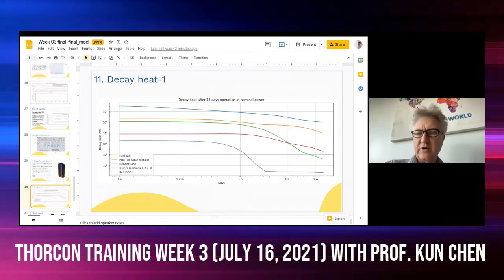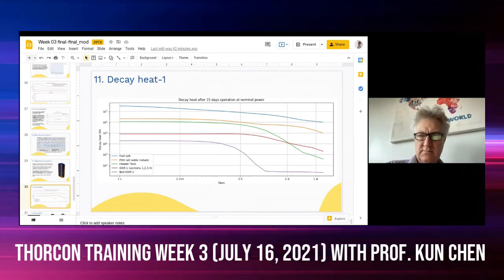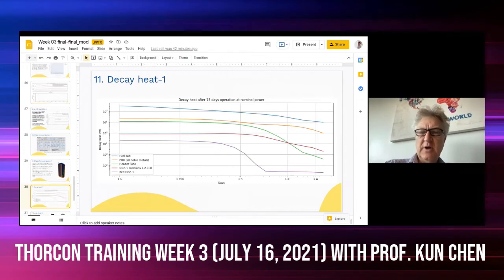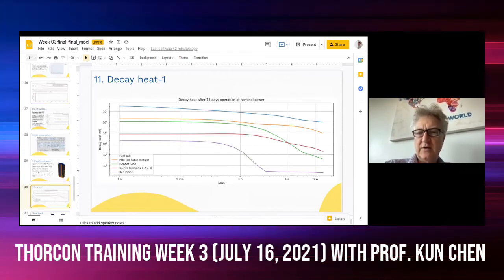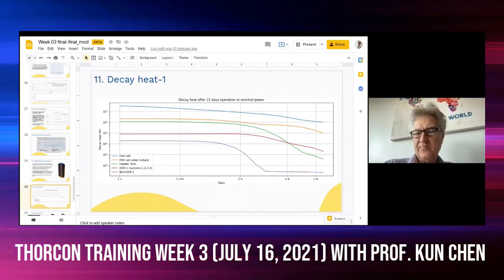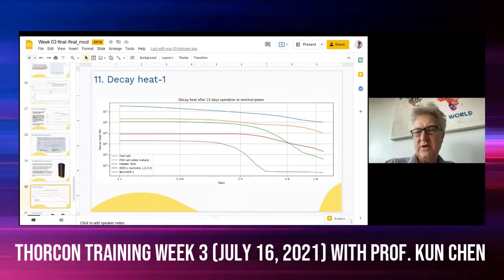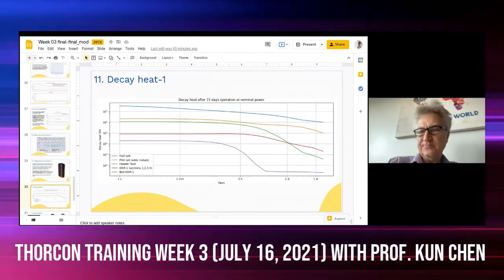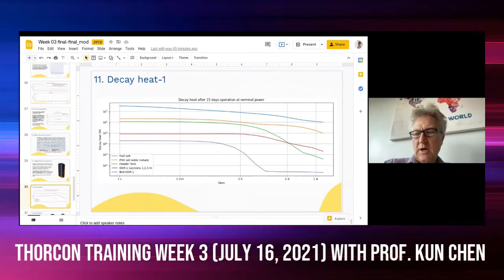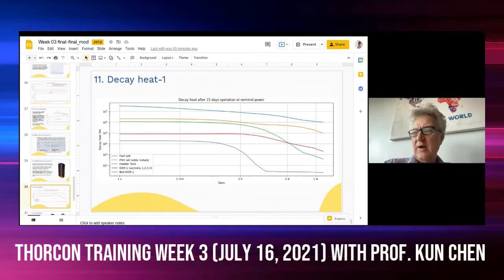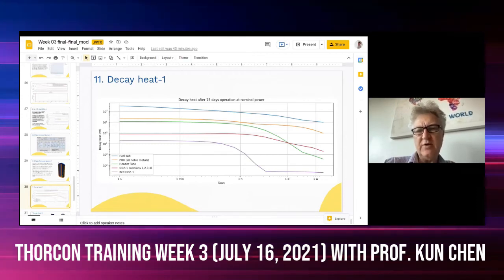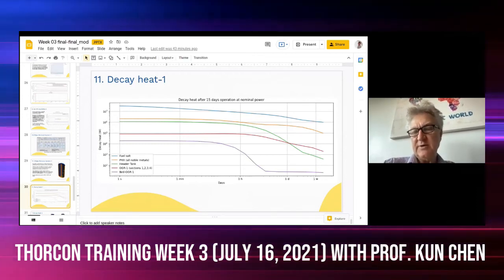Right. So that's driven by the turbine. When you get to the low pressure, the final stage of the turbine, if you go too low, then you start getting water droplets forming, and the liquid impinging on the turbine blades will wear them out. So somewhere around 30 to 40%. 40% is for sure okay, 30% is pushing things a bit.